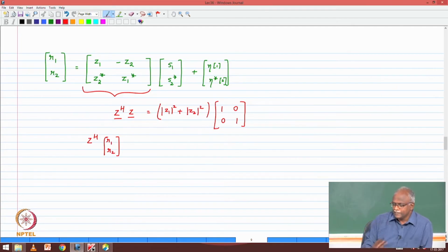So this is a very simple 2 cross 2 system where orthogonality was built into the transmission process, so that you could then detect the signal without any complicated signal processing, without having to do any interference cancellation. Basically, the orthogonality structure gave you the interference cancellation as part of the computation.